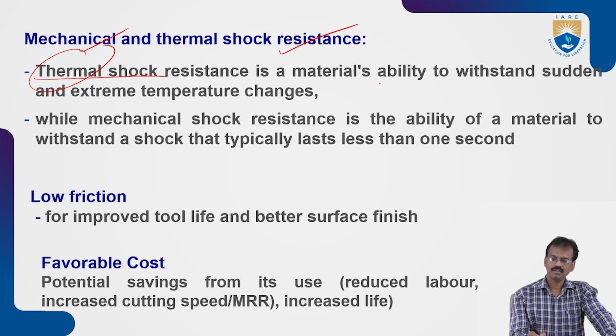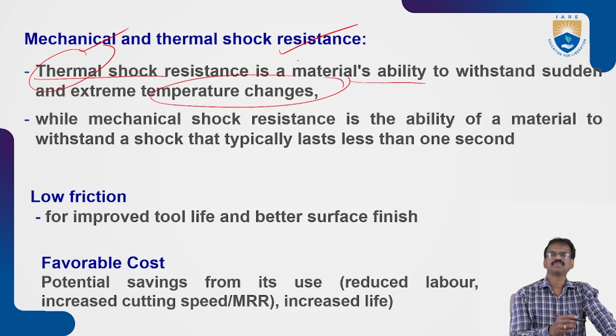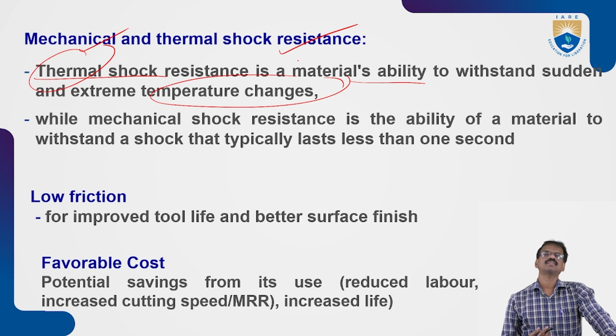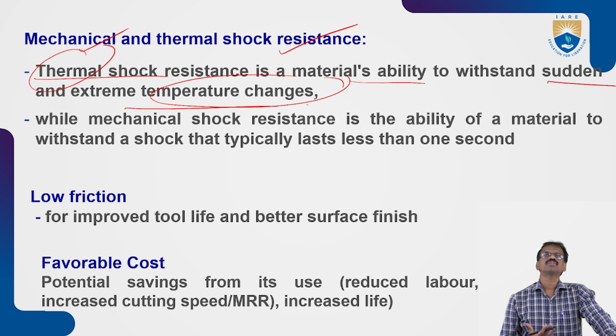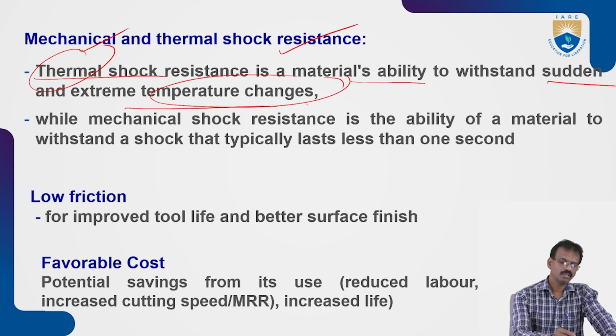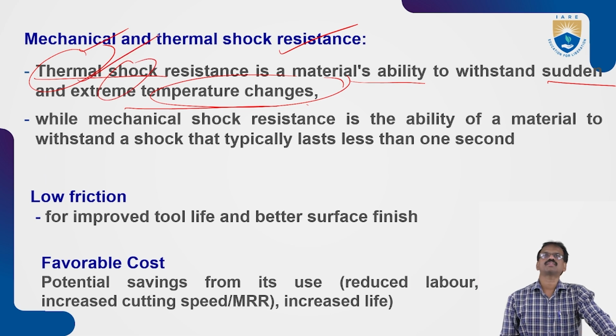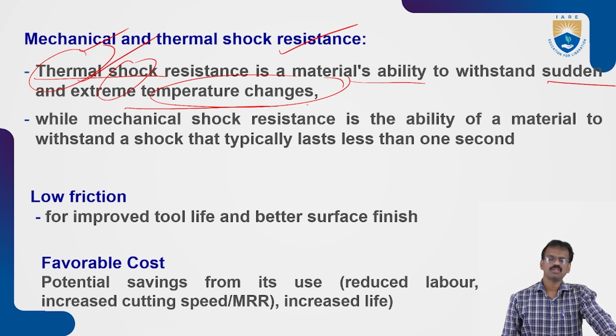So it is the material's ability to withstand sudden and extreme temperature changes. Sudden changes in the temperature. So in those conditions also the tool should have the ability to withstand those variations in the temperatures. So the cutting tool should have thermal shock resistance also.